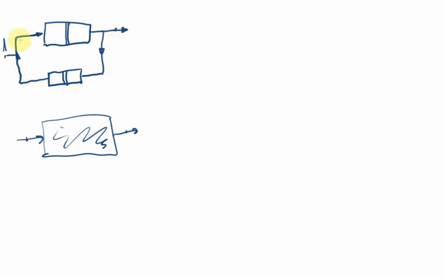The rest of this is considered to be part of the model that describes the actual mixing going on in here. So when we do the thought experiment, we are allowed to imagine a pulse input here, and let's see what happens to this pulse as it passes through the system. Remember, in our experiment we would be measuring tracer at the exit here, and we'd get some signal out, and that would be concentration in time. And of course we have E, the exit age distribution, which is the concentration divided by its own integral. We derived that relationship.